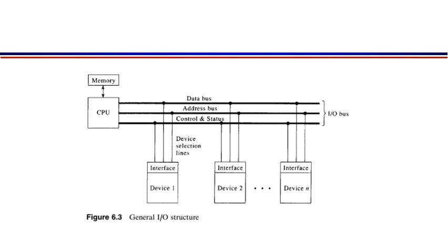All the devices will decode the address which flows on the address bus. The device whose address matches will act as the input or output device. In this way the selection of device will be done, and the CPU will be responsible to generate different control signals related to the input or output instructions.